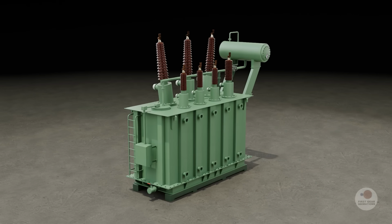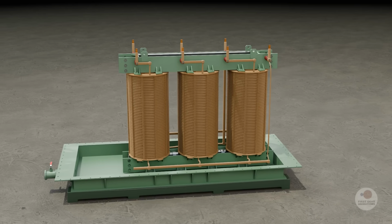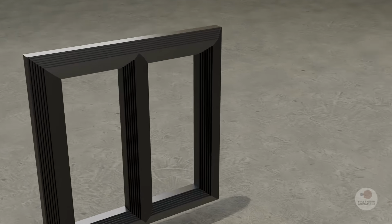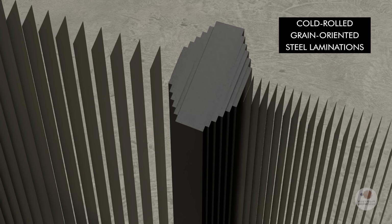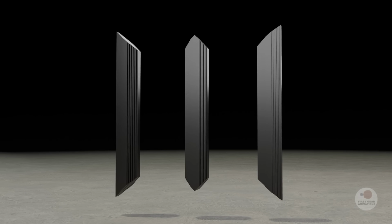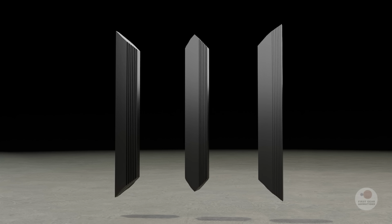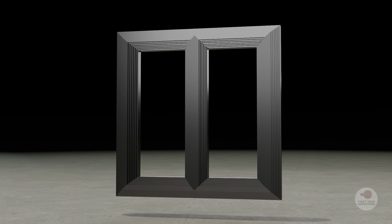Now let's build one from the ground up, starting with the core. The core is built from thousands of thin sheets of cold-rolled grain-oriented steel laminations, carefully stacked to form three vertical columns known as limbs. These limbs are connected at the top and bottom by horizontal sections called yokes, creating a complete magnetic circuit. If the core were made from a solid block of metal, the constantly fluctuating magnetic field would induce massive eddy currents, resulting in significant energy loss and overheating.